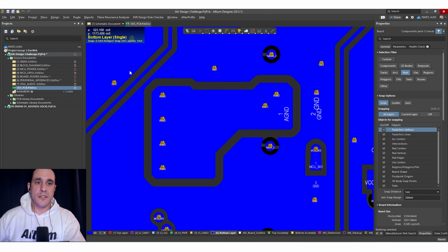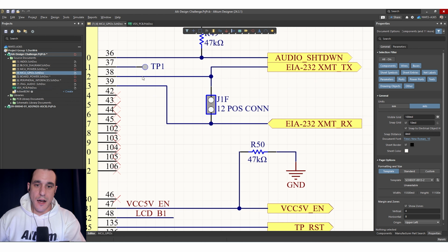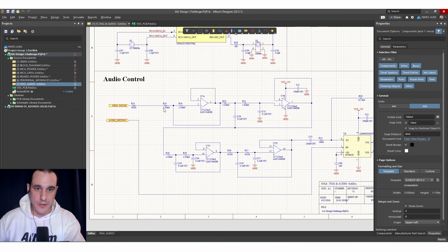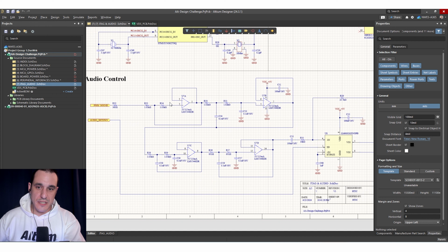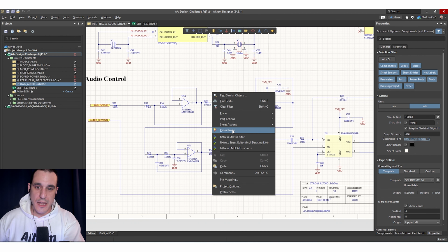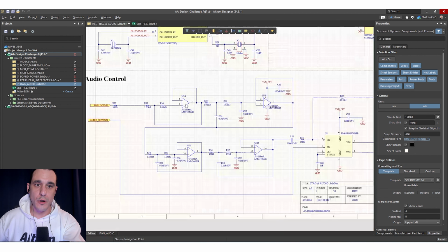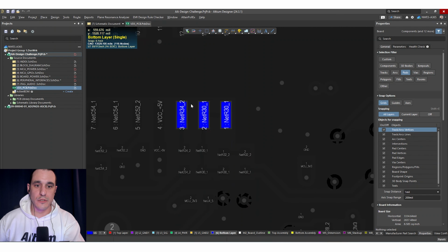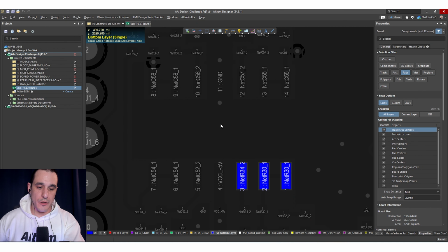The next thing that I want to look at is the audio interface, specifically over here in this part of the schematics. Here you can see we have this Butterworth filter and we have some amps, and they all share the same package. And if we just cross probe over to here, I want to see how this layout looks so we can see how well the return path is going to be confined and whether we might have a noise problem from any other signals.